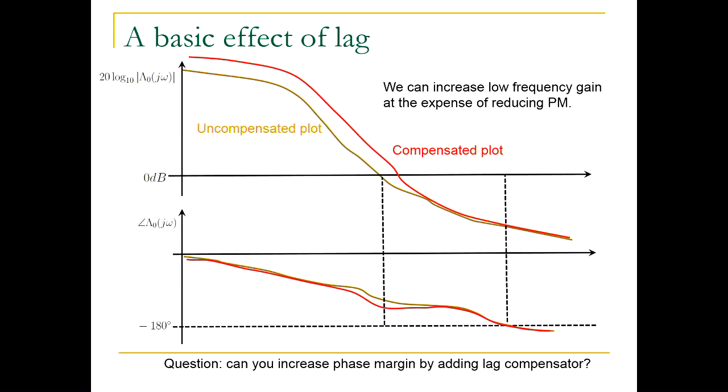Yep. Because it attenuates the high frequencies, you can move the crossover frequency to a lower frequency when the phase is better. So yes. Excellent. That's what I was looking for. Yes. So the answer is actually yes. You can increase phase margin.